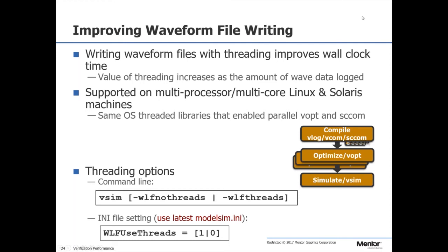And that brings up the question: is Questa multi-threaded? Is it helpful to have multiple CPU cores? By default, Questa is not multi-threaded. The simulation kernel is a single thread. The GUI, the wave window, on Linux, the WLF writing, those are separate threads, but the simulation kernel itself is a single thread.